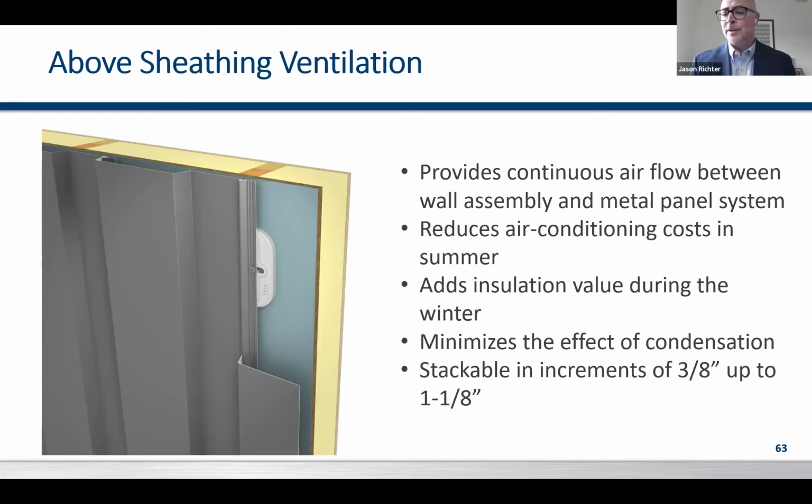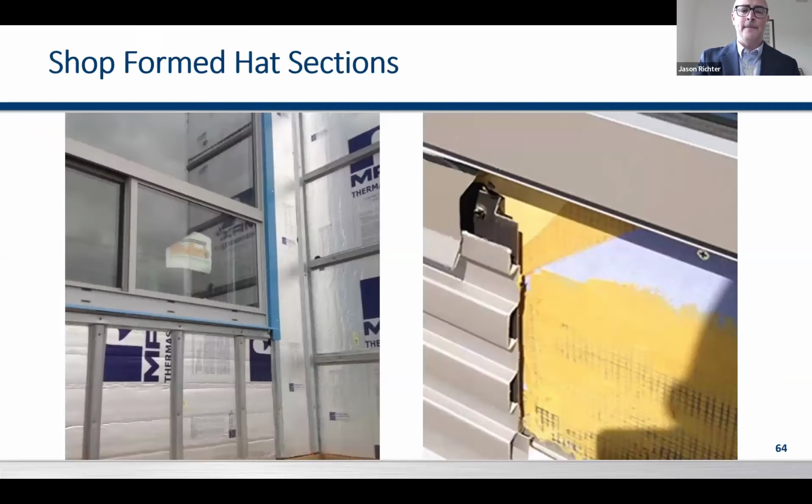In the exposed fastener world, we're dealing with panels that are 3 foot wide, and trying to line these up and get them to hit your valleys and your connection points on a 3 foot wide panel can be quite challenging. So we typically recommend keeping it with just concealed fasteners. But it does have to be on a structural panel. Otherwise, you're going to have them so close together, you might as well go with continuous supports there.